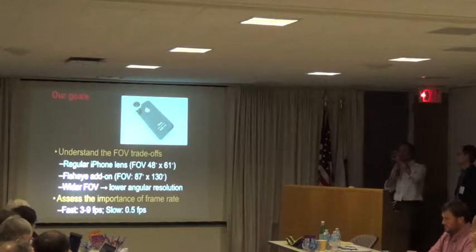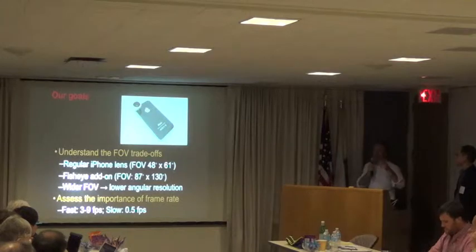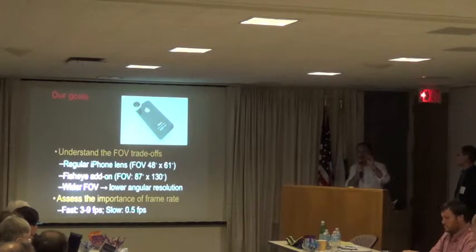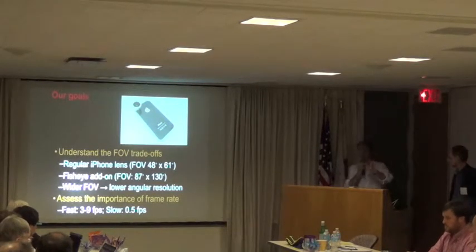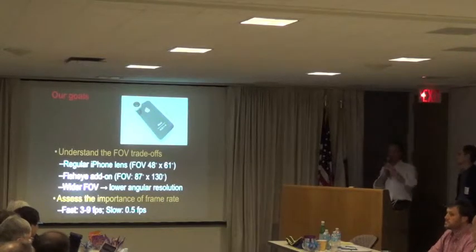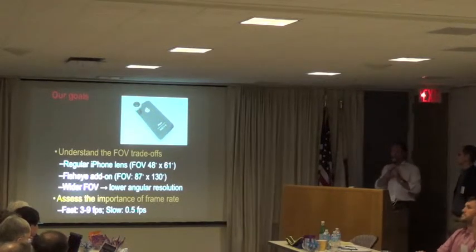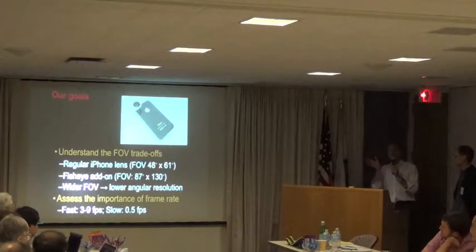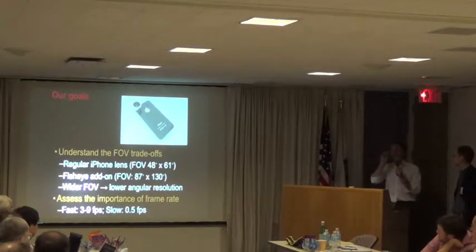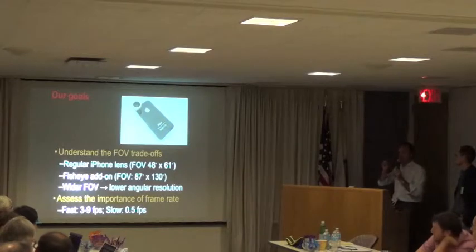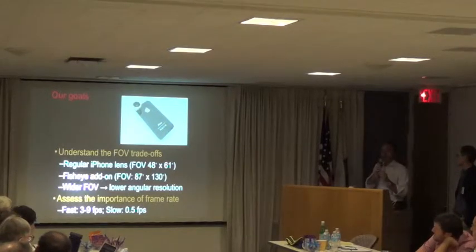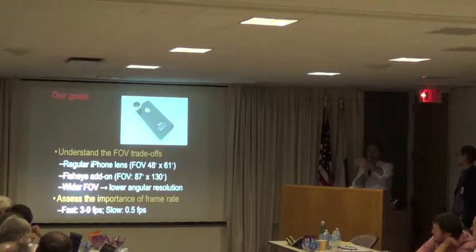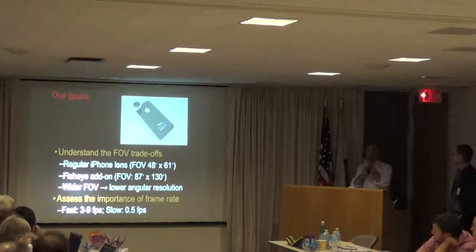So our goals in these experiments were to test the validity of this assumption that increasing the field of view for this type of guidance task can be useful. And we did a testing with or without this add-on. Keeping in mind, though, that if I increase the field of view of my camera, maintaining the same resolution, the same number of pixels, I am reducing the angular resolution. Basically, another way to say that, if I take a picture of the same object from the same distance with a camera and with a camera with a large field of view, the second picture shows the object smaller.